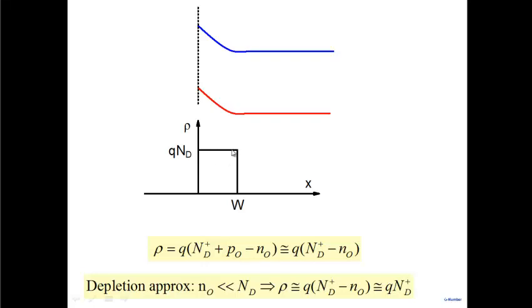Okay, and this approximation we'll see is a widely used approximation. It's called a depletion approximation, and the width that we'll get and we'll use at various places is a fairly good estimate of how large this region is here. A more accurate word for this region next to the interface is not depletion region but a space charge region, which is obvious from its name.